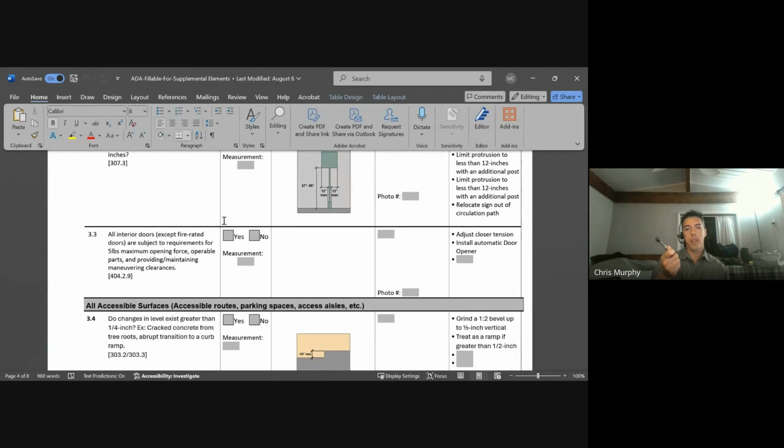If you push on the door closer to the hinge, it's going to require more force because you have less leverage. If you push where the handle is, you're going to get an accurate representation of the opening force. So that's one very important aspect of how to use this. Push on the door where you would push with your hand. Use your best judgment, and make it make logical sense in that regard.